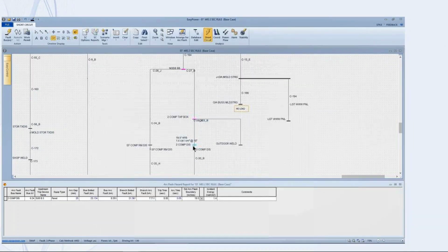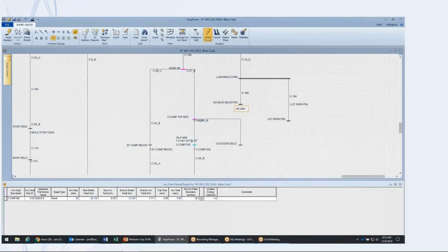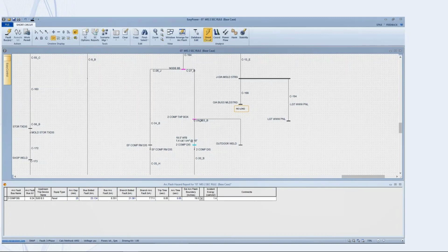So in this case, by applying the 2-second rule, I've actually obscured the fact that we have miscoordinations and the ability to mitigate the incident energy on a bus that is a real hazard, and frankly provide some measure of protection if we need to work on that system. So again, it's a misapplication of the rule, and I think it bears notice for someone doing the study.